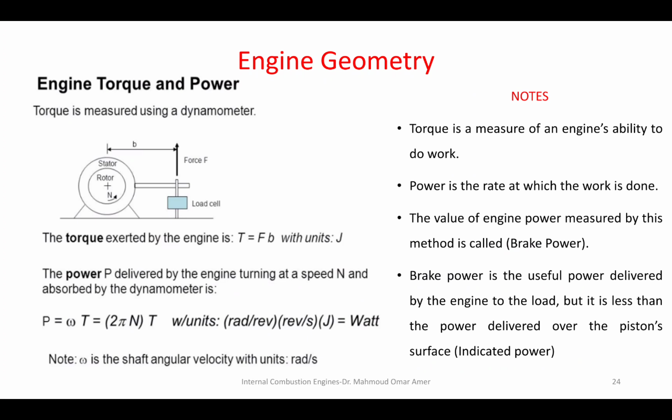Of course, you know that torque is related to power, as power equals torque times omega, and omega is 2 pi n. And of course, as in all calculations, as I mentioned, n is in what units? Revolutions per second, not minutes, because we use SI units. They do not consider minutes. They consider only seconds.